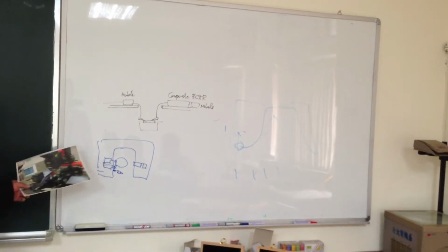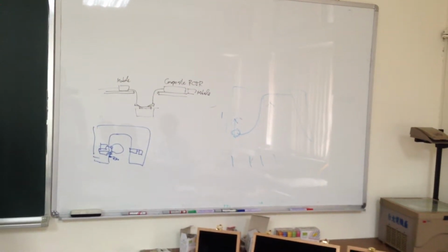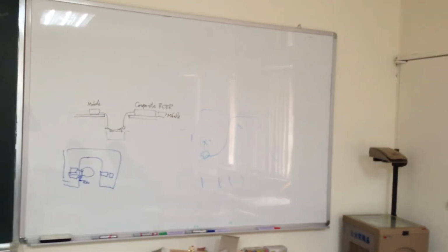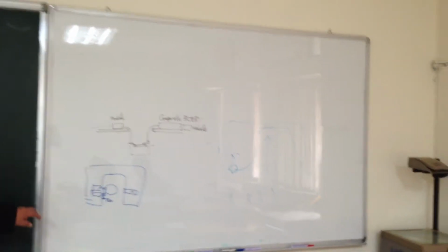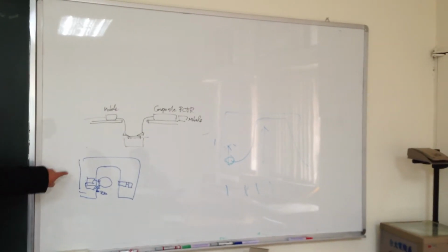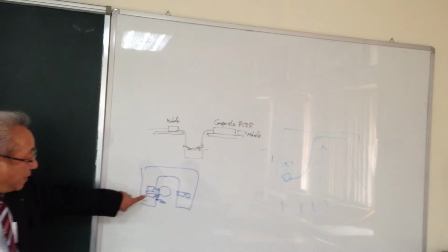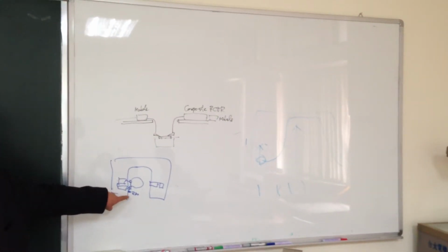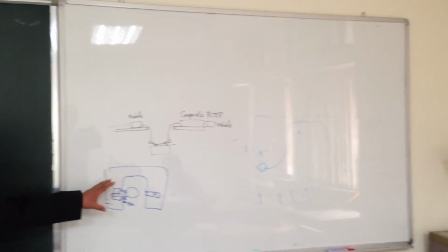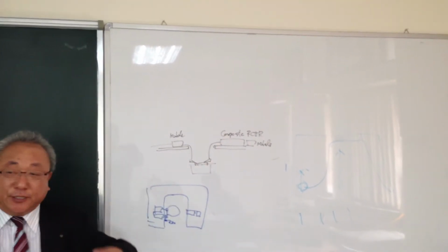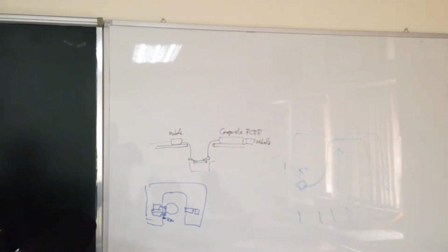So that is one idea. If they are using the compact millimeter wave module, then maybe you can set some standard positioner on the flat thing, maybe two or three. Then one is the probe tip with terminator here. Then for the measurement, the chuck is moving to the other probe.